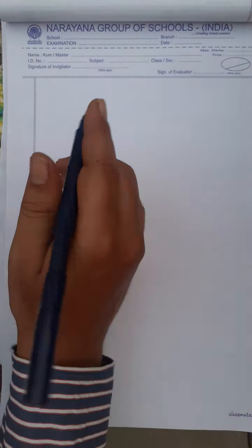So polar NRZ, this is a time axis T, TB, 2 TB, 3 TB, 4 TB, 5 TB. This is a voltage level I referred, plus 1 and minus 1 volt. We know that polar NRZ, polar means here bit 1 is mapped to plus A volts, that is plus 1 volt. Bit 0 is mapped to minus 1 volt.